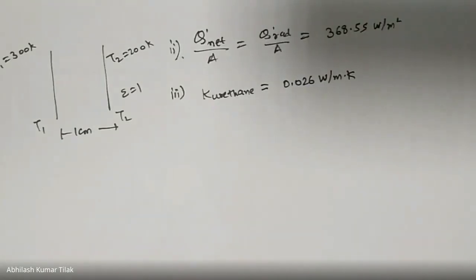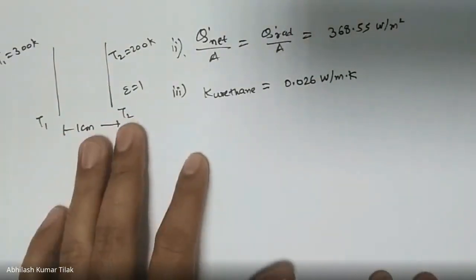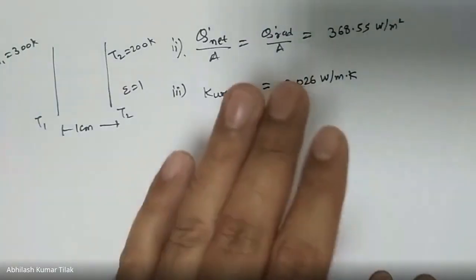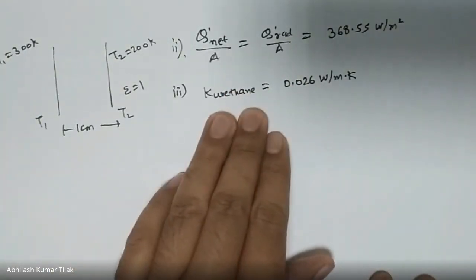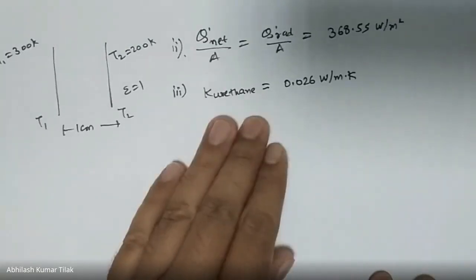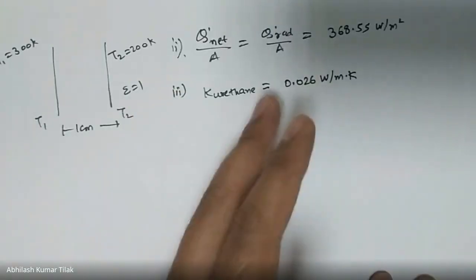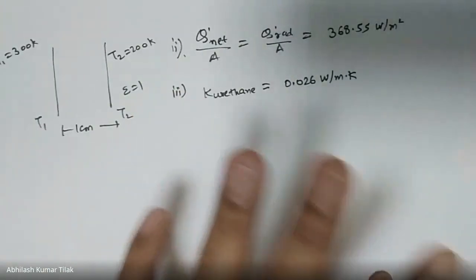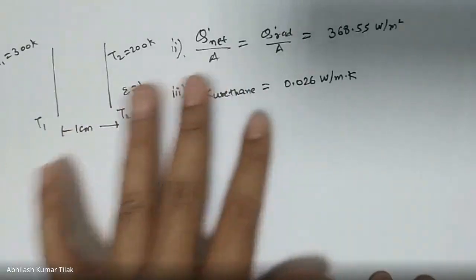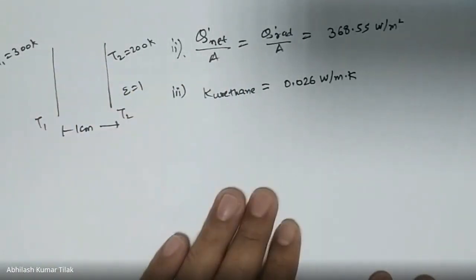Since there is an insulation, mostly it will be by conduction. So the radiation heat transfer can be considered in the thermal conductivity of the urethane itself. When we are determining the thermal conductivity of the insulation between two media, whatever the radiation heat transfer is can be considered in the value of the thermal conductivity itself. We will have a detailed discussion of it in the radiation chapter.